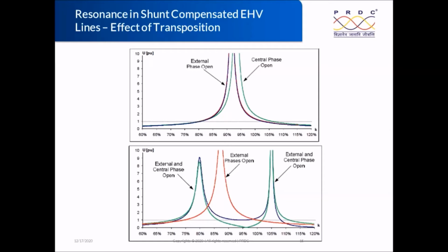Okay, so what will happen, because that looks compact compared to your regular 400 kV tower. So if the tower design is a compact design, meaning the phase conductors are placed very close, then your capacitance values will increase. For example, in the case of a cable, we have the uniform and trefoil formation for the cable.